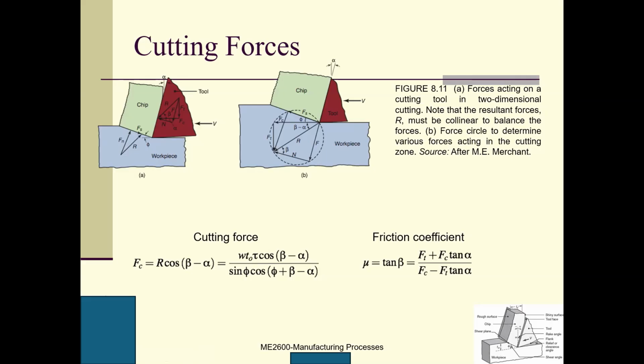So here is the resultant. This is the resultant force. We know if we apply the external load, the workpiece will give us a reaction force. The reaction force can be decomposed into Fn and Fs. So we suppose this is the resultant force.